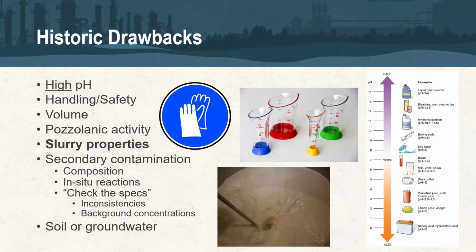anything that was more traditional, going back to the early days of CERCLA, where we transitioned away from dig and haul into more treatment and Subtitle D disposal or on-site disposal. We borrowed heavily from a product standpoint of what we would look at to inject in situ. A lot of those early products were lime-based. They were pozzolanic. They typically were very well suited for their applications in soil mixing and T&D, but not necessarily for specifically groundwater treatment or in situ injection, just from a practicality or equipment standpoint.